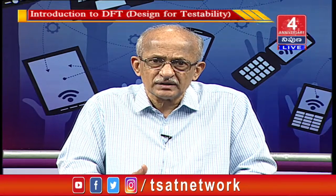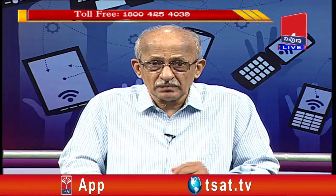How can the chip work at 1 gigahertz? Internally to the chip there might be a PLL, a phase lock loop, which takes in a 100 megahertz clock and generates a 1 gigahertz clock internally by doing frequency multiplication. Having done that, it applies this 1 gigahertz to the chip, and mind you, not all parts of the chip will work at 1 gigahertz.